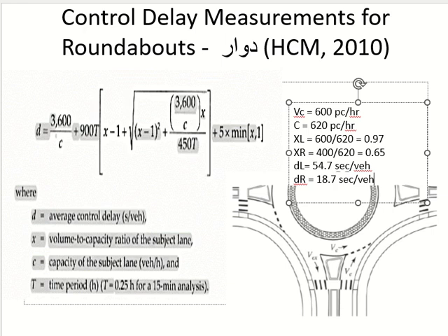Okay, so both lanes have the same design, because their capacity is the same. But their delay is higher in the left hand side lane. Why is delay higher in the left hand side lane? Because of its flow. If you compare between them, the difference is almost 3 times. If you look at the flow, it is only increased by 30% something. So the delay increases exponentially when the flow increases. The delay does not increase by the same amount.